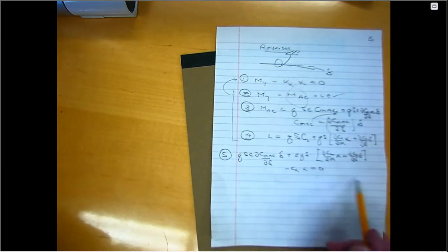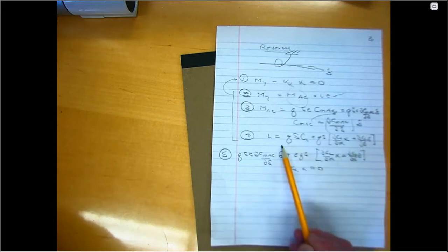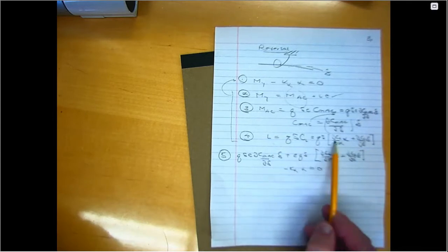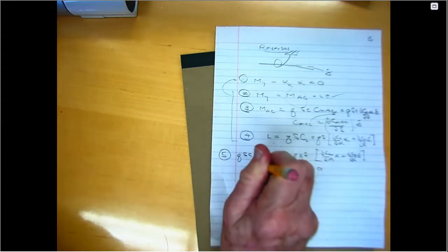Now, that's interesting to do. I may actually do that at the home assignment sometime, or maybe in the following class. But I'm going to bypass that calculation in the following way. Remember, reversal by definition is when the lift is 0. So another way to do it is I can take advantage of it. I can set the lift to 0. That gives me an equation relating alpha and delta. And then I can put that in this equation.